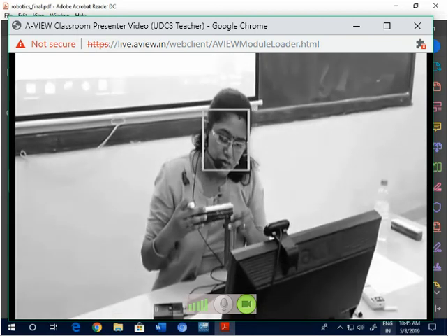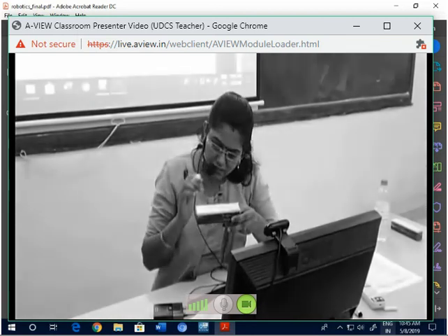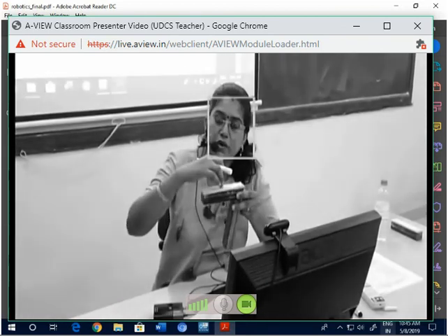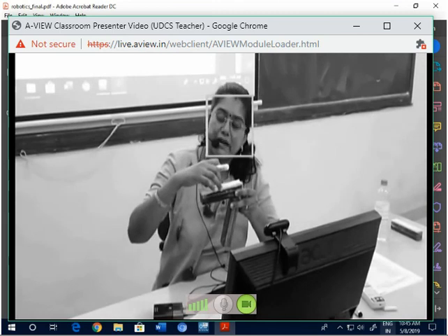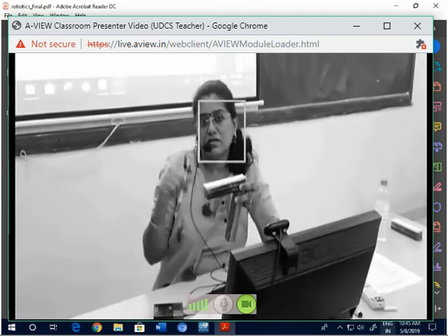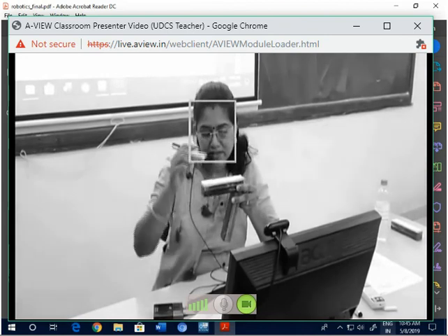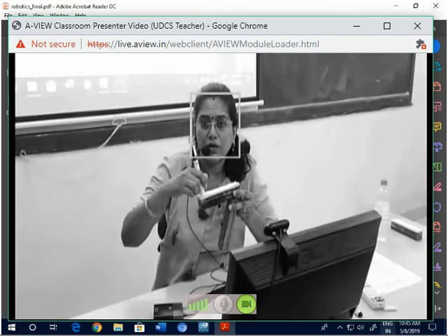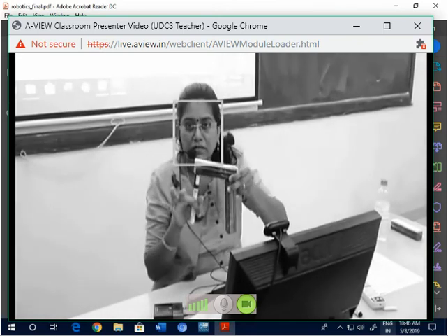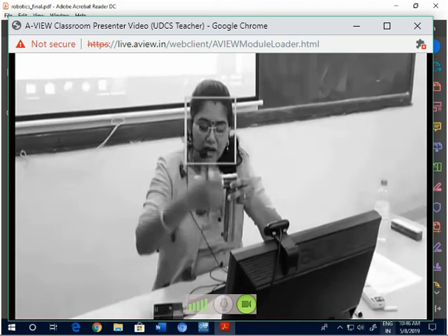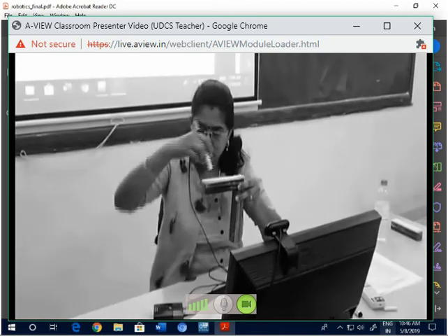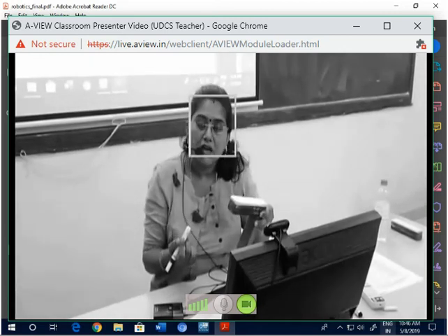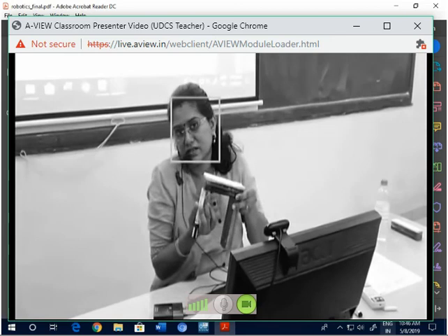Tool angle, that is, the tool pitch which was present after the elbow. Now if that angle also changes, the position of this tooltip will change, because this is the elbow out here, you have tool pitch here, you have tool roll out here, and you have the tool gripper out here. So you have one rotation out here, you have one rotation out here, and you have one change in the position of your point P, the gripper axis of operation will change.